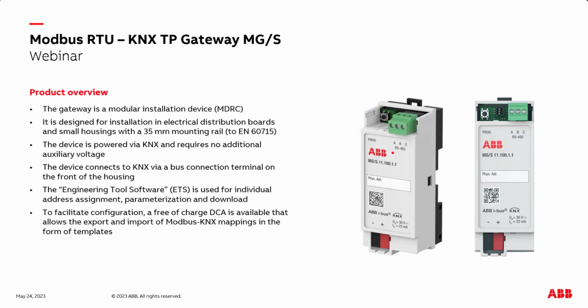But the device can use up to 22 milliamps from KNX. So when you plan an installation and calculate the number of devices, please be careful, it counts as 2 devices because of the maximum 22 milliamps. In principle it is a standard KNX device with our KNX bus connection terminal and a typical programming button and an LED.